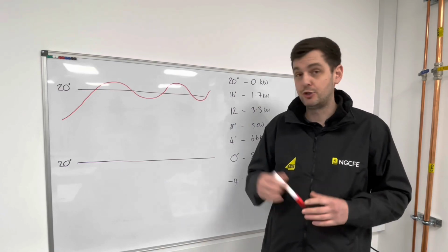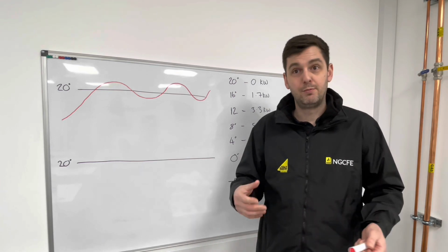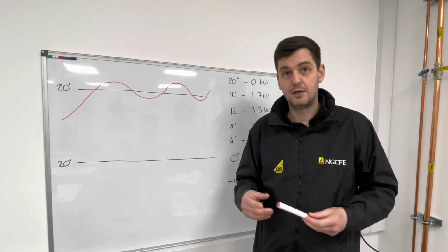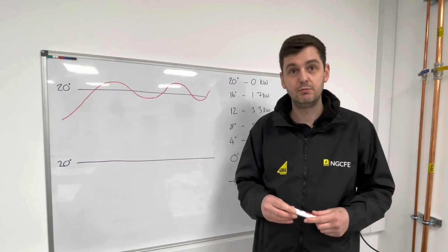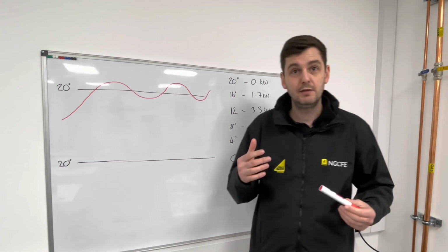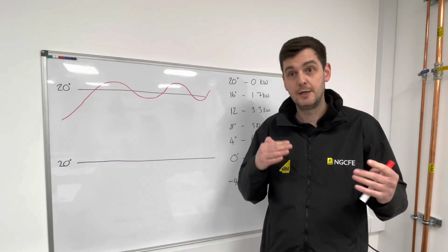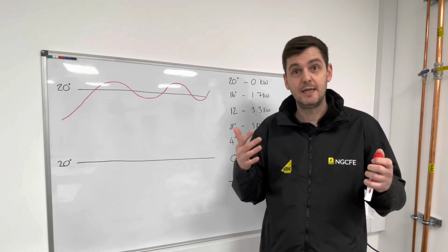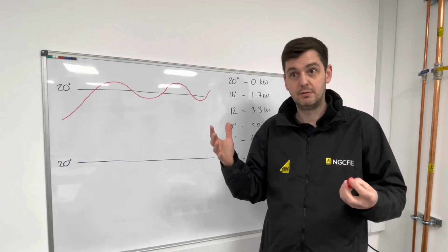So it's not desirable. So we've also got on-off modulating controls, which again do something similar, but they are slightly more efficient. Load compensation, which is what you generally get with OpenTherm, is where our boiler and the control is constantly speaking to each other, and your control tells the boiler how hot the water leaving the boiler needs to be in order to get to the set point that we've got in the room.